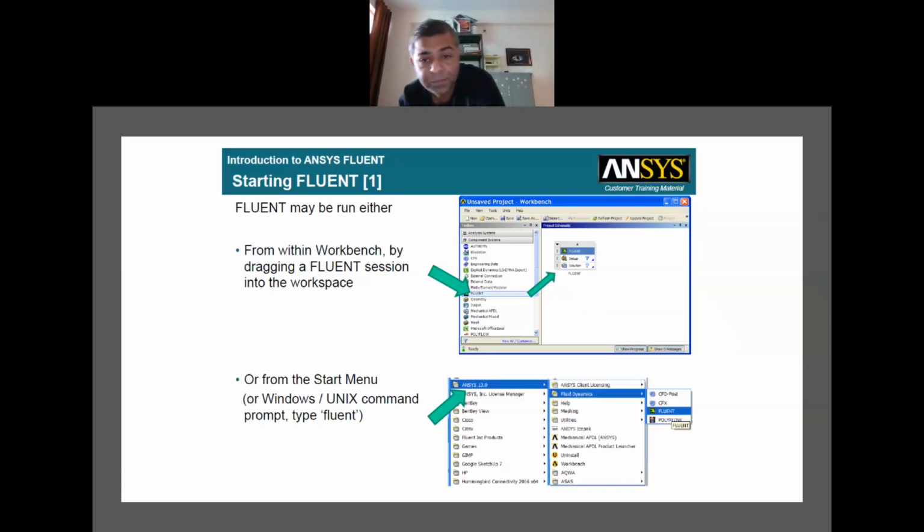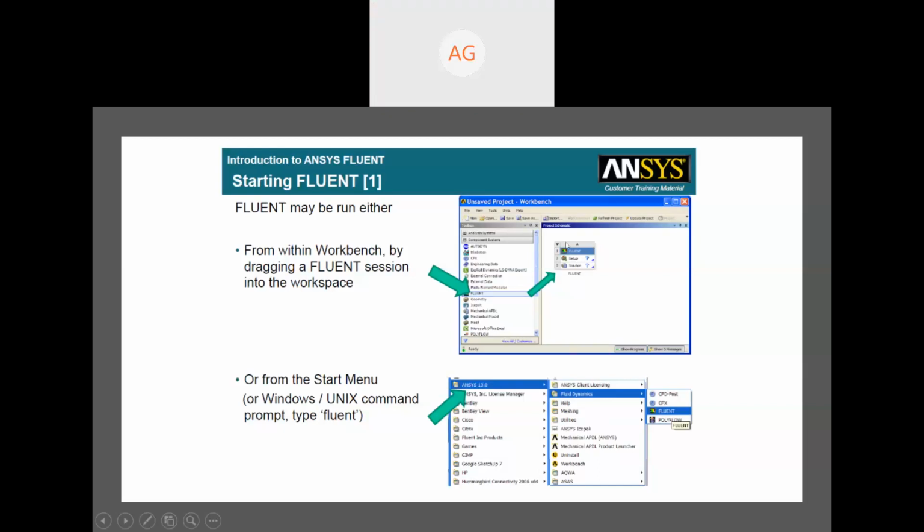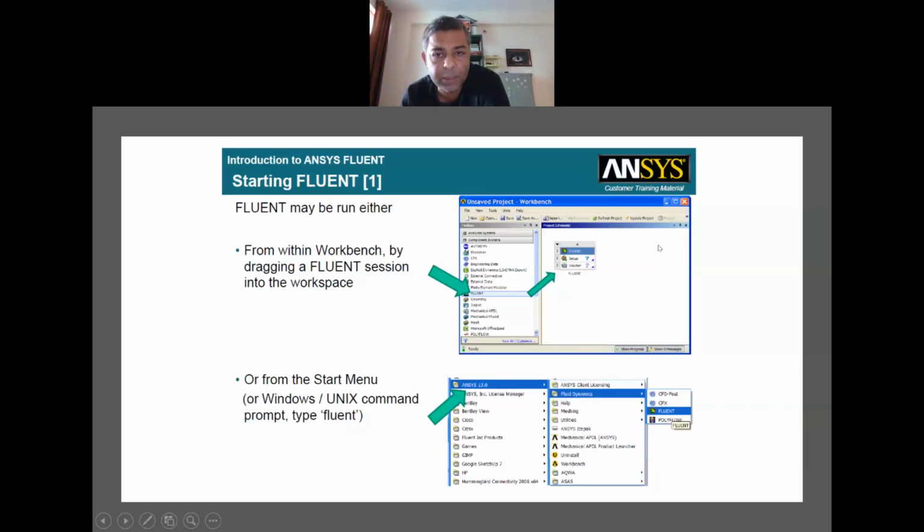Okay. So this Fluent window will come in this project space. Fluent is written as Setup, Solution, it will come also. Now two more things will come if you have to set geometry, make a geometry, and meshing. So two more windows will also come here in this Fluent setup. Also you can run through the command prompt: go to the Ansys folder, select fluid dynamics, and there the Fluent exe is there. You can run from here also.